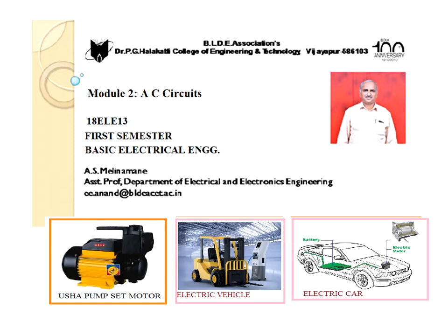Number 1, in a pure resistance AC circuit, phase angle is 0 and both voltage and current are in phase, and power equals V into I watts. Number 2, in a pure inductance AC circuit, phase angle is 90 degrees, that is, current lags the applied voltage by 90 degrees, and power equals 0.